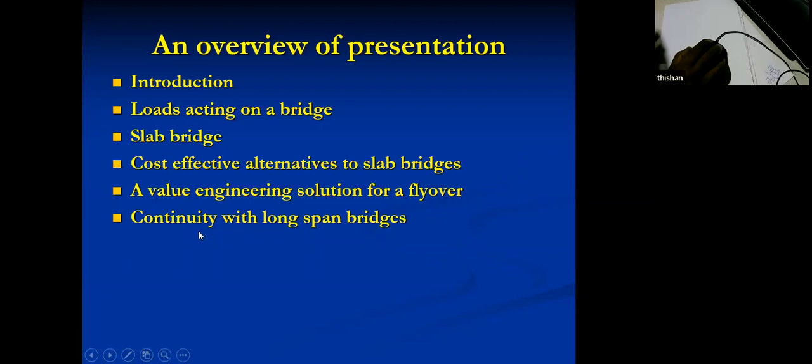And then another topic that is very applicable today, where we have so many elevated highways and expressways. For example, on the Outer Circular Road in the Malabe area, you can see the road is elevated. The reason is it's a floodplain. With elevated bridges or expressways, we need continuity to avoid expansion joints. For about 5 to 6 spans we have only one expansion joint, and for the other spans the bridge is continuous. So continuity is a very important topic in today's context.